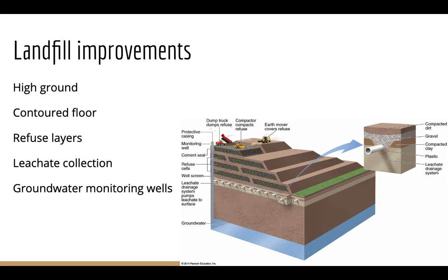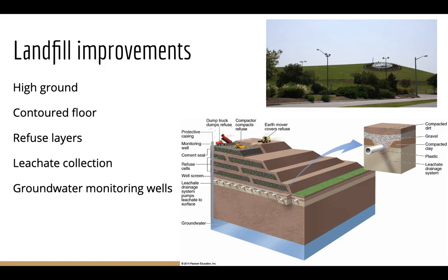Stuff that shouldn't go in a landfill: metals, aluminum, copper, stuff that could contribute to leaching, toxic materials, consumer electronics, appliances, batteries, substantial metals. All of those things can create toxic leachate. Organic materials can be a methane source. You want to avoid putting organic materials into the landfill as well, and they can cause that settling problem as they decompose. So this is Mount Trashmore again.